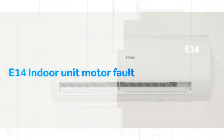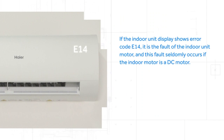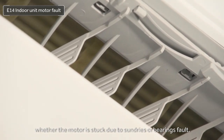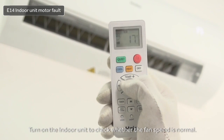E14 Indoor Unit Motor Fault. If the indoor unit display shows error code E14, it is the fault of the indoor unit motor, and this fault seldom occurs if the indoor motor is a DC motor. Remove the flap and check the crossfan to see whether the motor is stuck due to sundries or a bearing fault. Turn on the indoor unit to check whether the fan speed is normal.